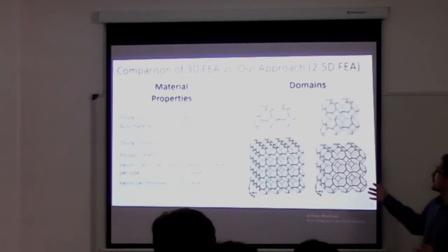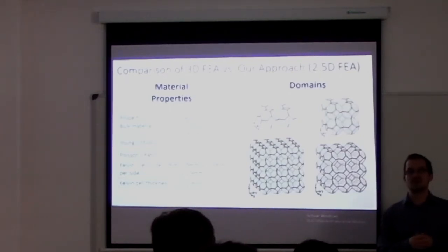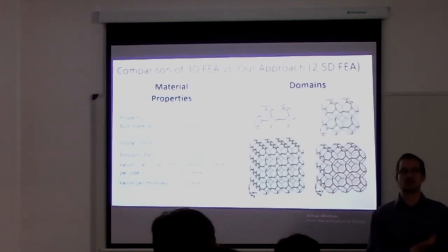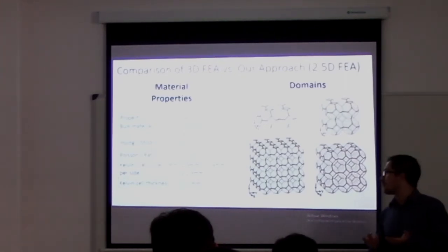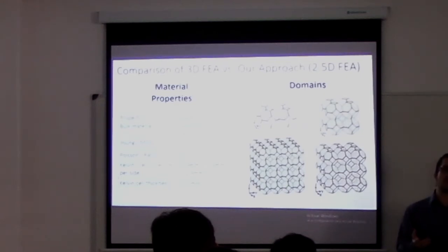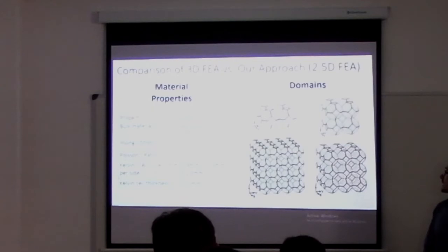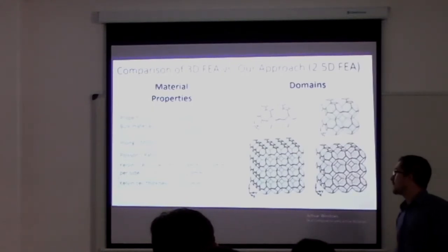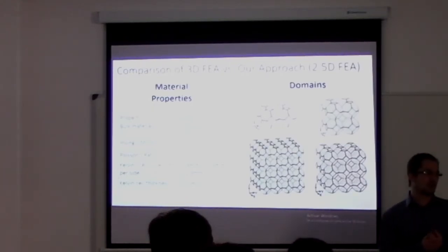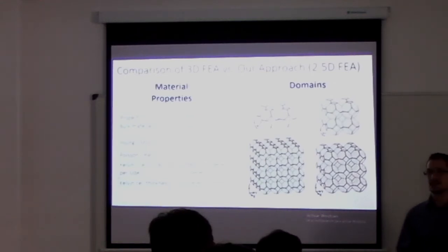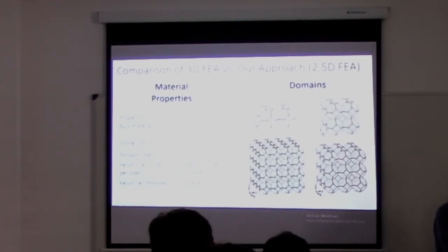These domains have a main characteristic for us: they may be simulated using the two approaches, our approach and the approach of using 3D finite elements. We simulated aluminum with a Young's modulus of 71 gigapascals and a Poisson ratio of 0.3. And our Kelvin cell has a size of 1.9 millimeters and thickness 0.1 millimeter.